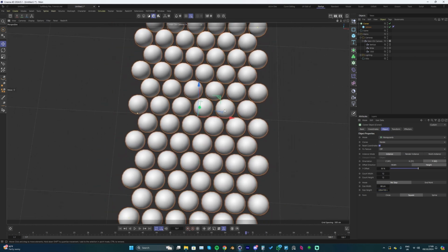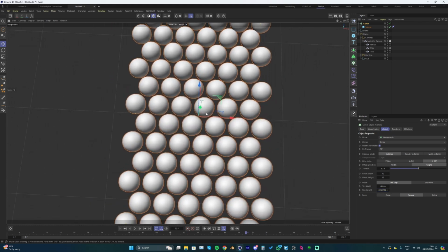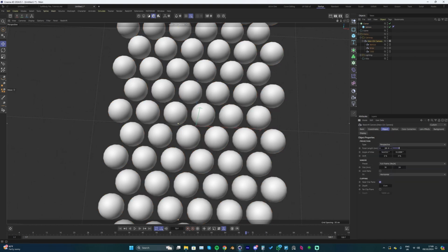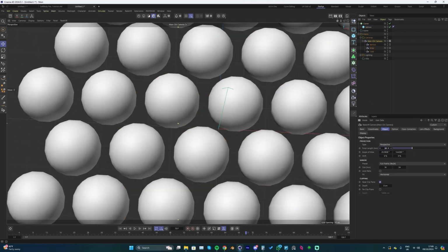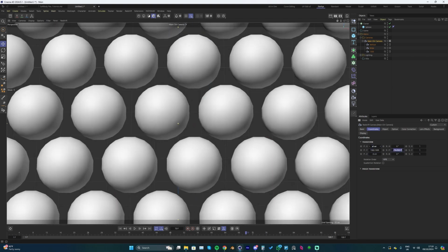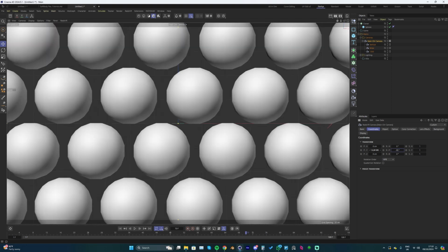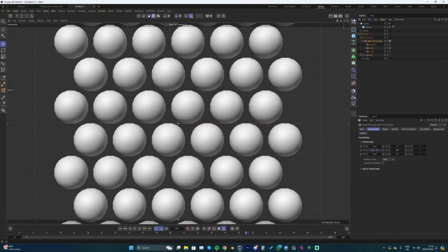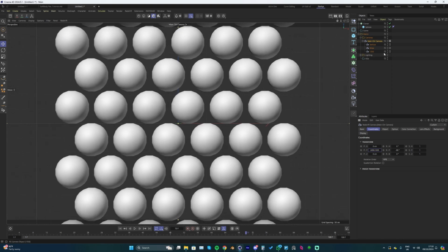And we might as well just set up our camera whilst we're here. So if we select our camera, main camera, I'm going to change the focal length to 80 to begin with, and then just zero out the X, the Z, and then just zero out the rotation. Actually no, change the P to -90, and then we just want to kind of raise up this camera to create a frame. This will do.